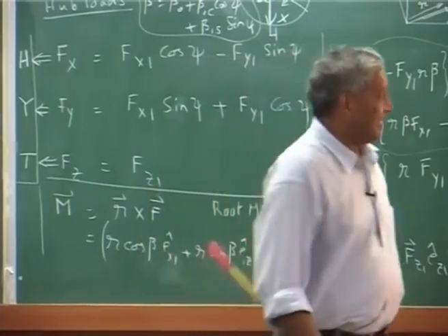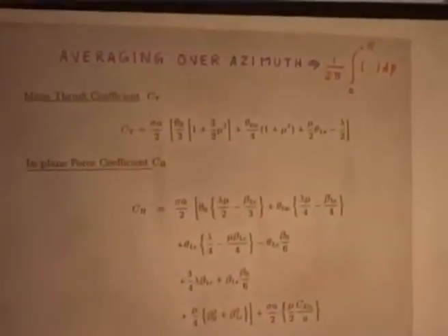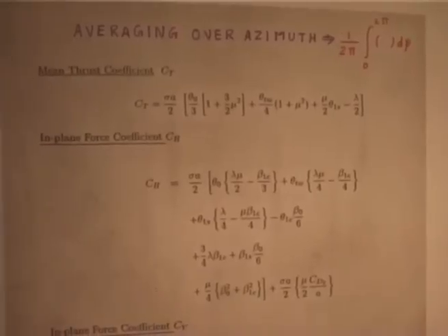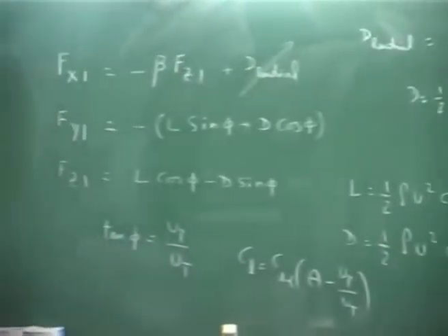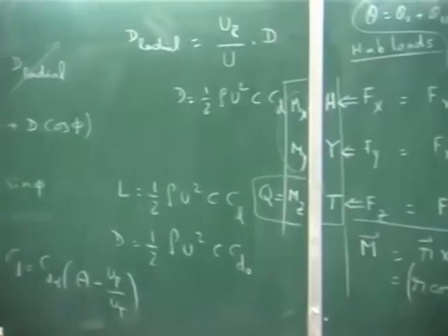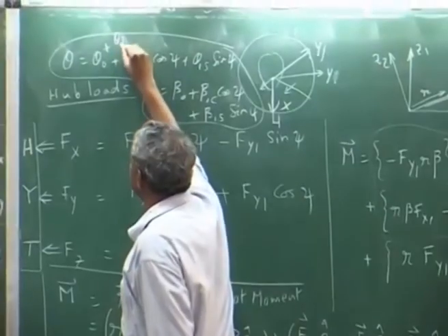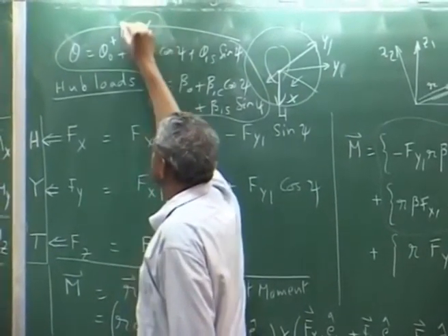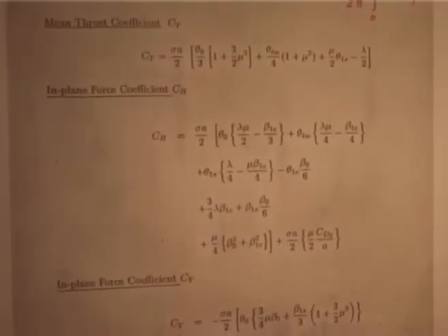And just to give an idea of the minimum equation you can have a look at, it is this. With all these assumptions, and you make the small angle assumption, neglect phi also, you make it small, and you get Ct. Twist is added, you can add a twist also, plus theta twist r over R. So, this is my thrust, the mean value of the thrust, please understand.